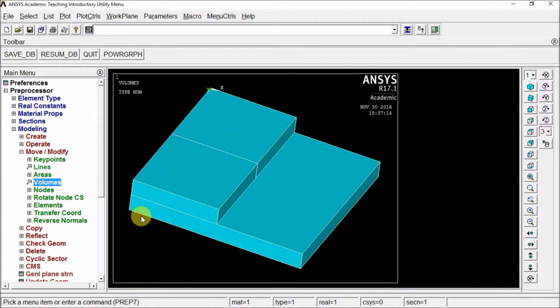I'm going to be going over how to do contact pairs. So I've got this unique block figure here. I'm just going to do a contact pair between the top two blocks and the bottom plate. Often with contact pairs, you're going to have two surfaces that are touching, but you can't really see the interface. So I can't see the bottom of this block and the top of that plate where it's touching.